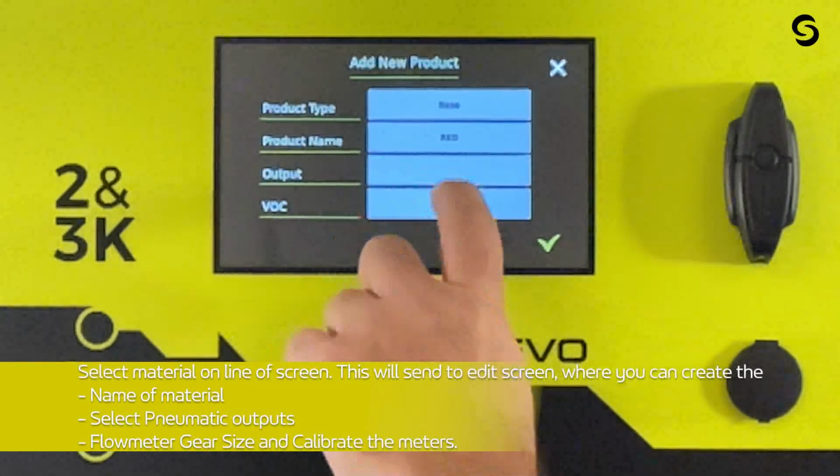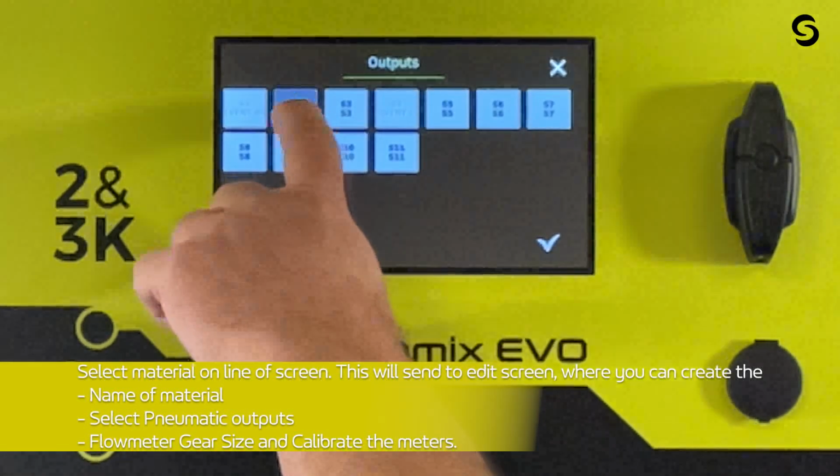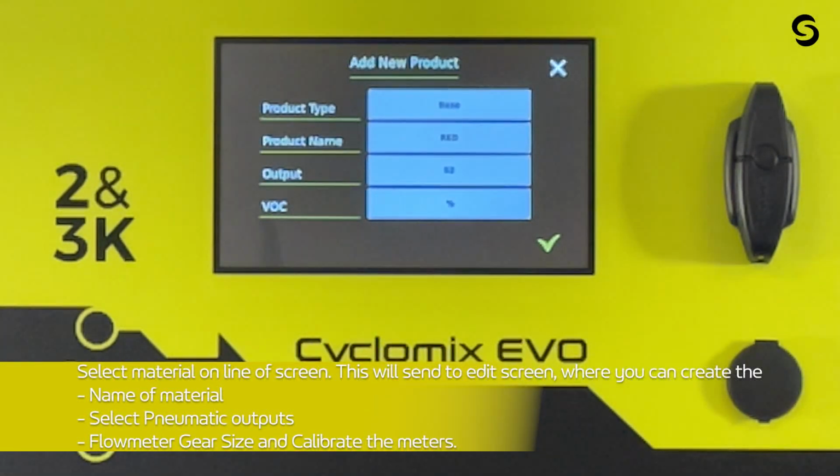And then I need to select my output. Now remember, when we set this up earlier, our first output was going to be solvent, and then our second one is going to be our first color. So I'll select 2, hit the green arrow to validate, and now I'm on output 2 for this color.